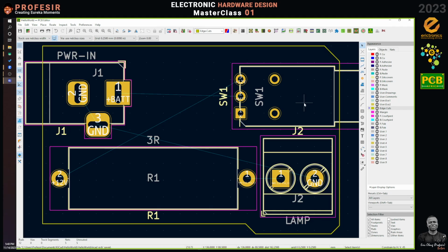So if we are going to etch it locally, then ideally it will be easy to create it as a single-sided board. Because actually we are not even doing any long stuff here, so we'll just do it as a single-sided board. The first thing I like to do is edit the board setup. So you click on this particular button here, it will open what we call the board setup. Click on the second button here, the green one. It is trying to open.